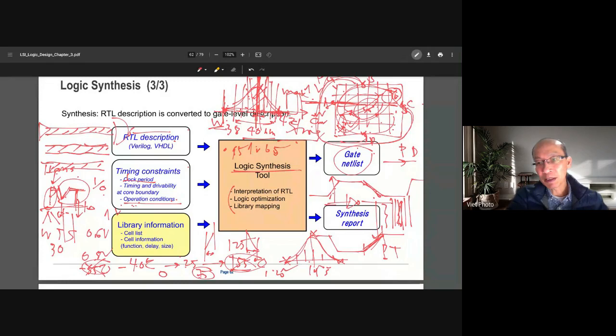Because when the width varies, the wire resistance varies, right? Also the wire gap varies, whatever the wire varies. When the temperature varies, high and low, the resistance will change, right? So the PVT here is for the cell library, and the PT here is for the middle wires.